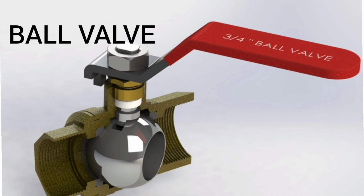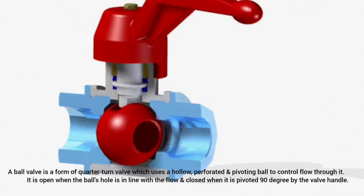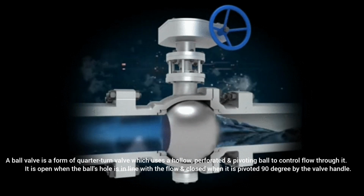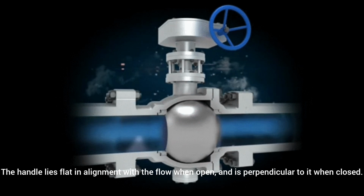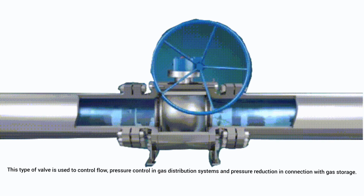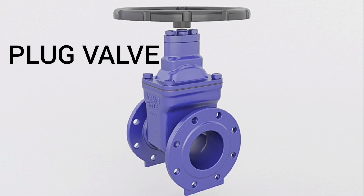They have two openings in the body, one for fluid to enter and the other for fluid to leave. Next, ball valve. A ball valve is a form of quarter-turn valve which uses a hollow, perforated and pivoting ball to control flow through it. It is open when the ball's hole is in line with the flow and closed when it is pivoted 90 degrees by the valve handle. The handle lies flat in alignment with the flow when open and is perpendicular to it when closed. This type of valve is used to control flow, pressure control in gas distribution systems, and pressure reduction in connection with gas storage.